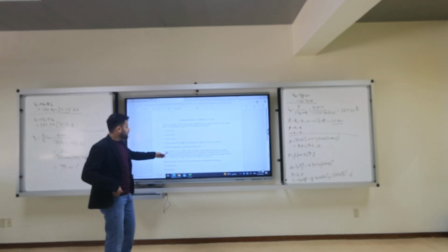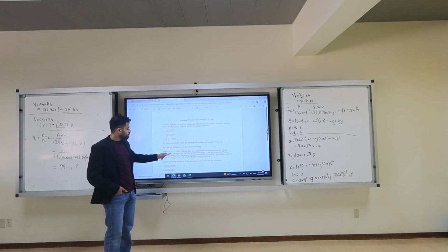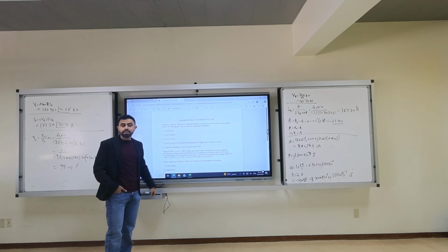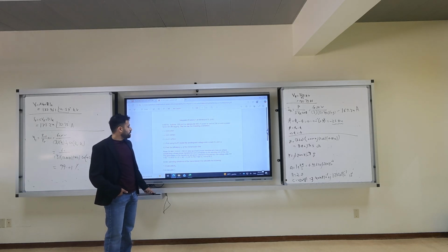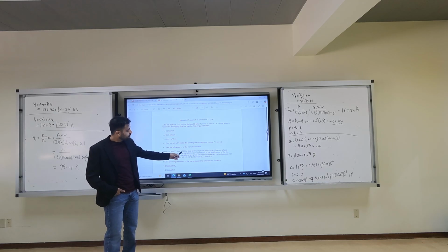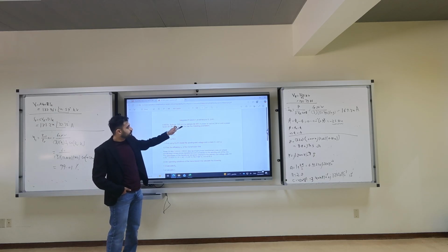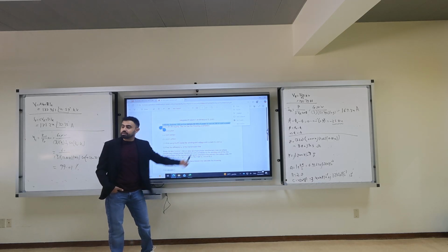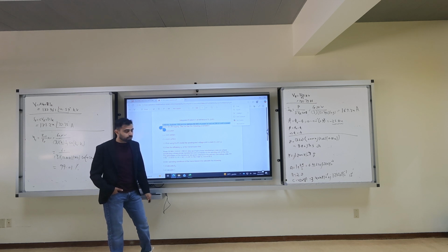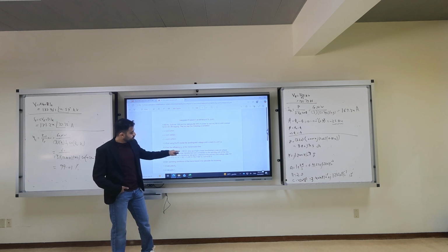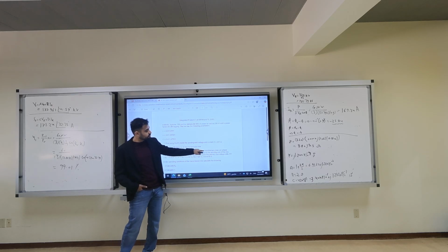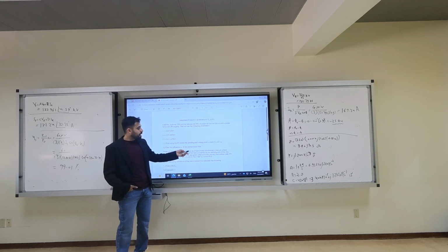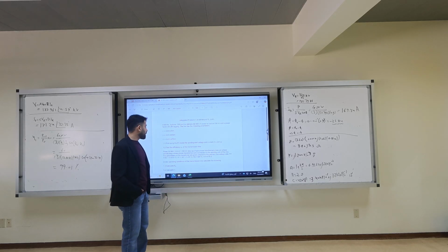Three 20 megawatt single phase transformers. 3 times 20 is 60. But do they satisfy the design? Yes. 13.8 to 230 kV. 230 kV is the line level, line to line. So this transformer is before or after? Before. So 13.8 over 230 kV step up single phase transformers, one per phase constituting a 3-phase transformer, are connected to the sending end of the line, of the transmission line.